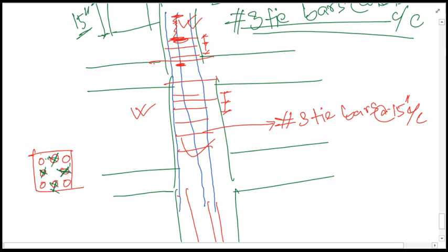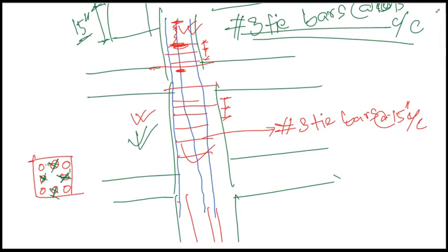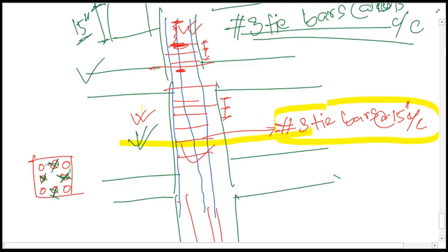And to maintain, this is the practical design aspect which you should maintain, you will have to show in longitudinal section. And from there, if I say the minimum thing, this is the cutoff you will have to show. So while showing in section, this is the longitudinal section. When transverse section, you will take a section from this one, usual section as designed. Another section you will be taking close to the joint to show this spacing in the transverse section.